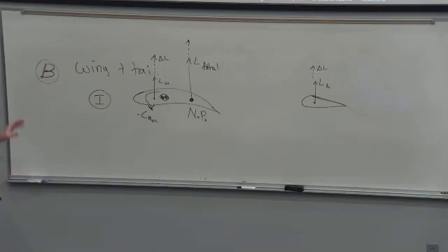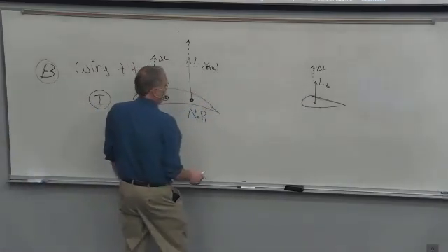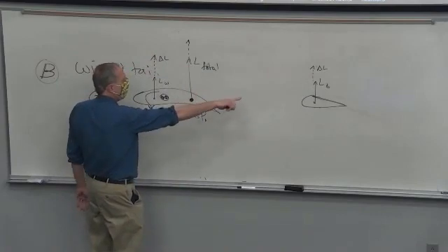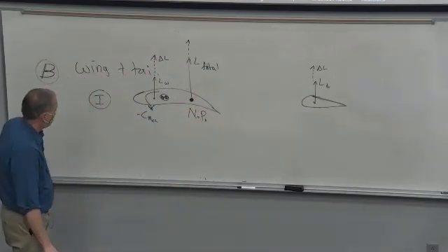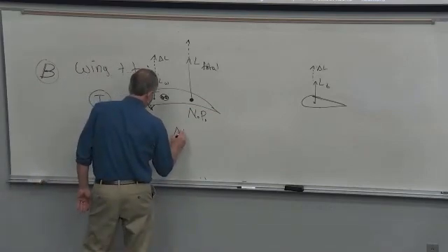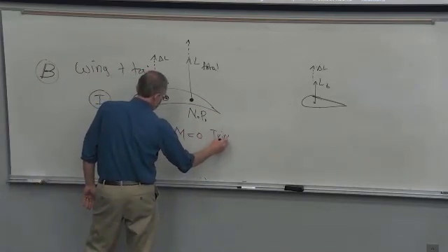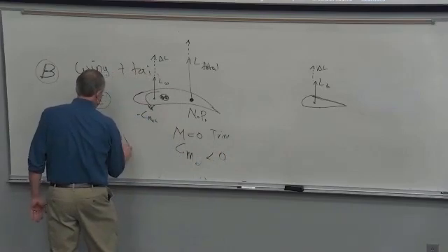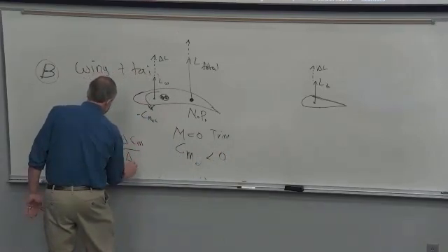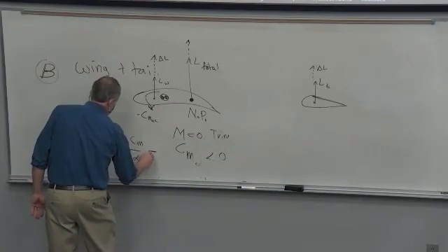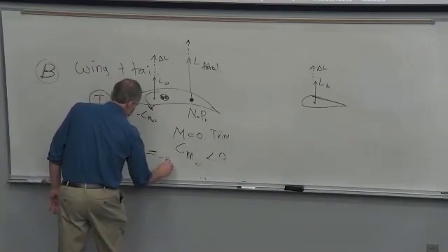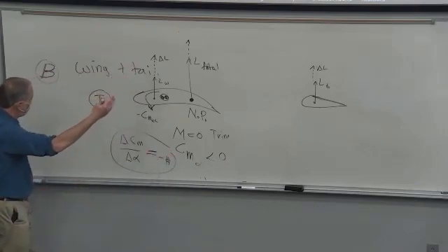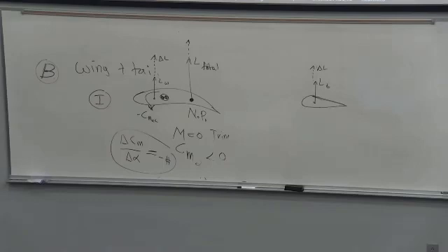And it's the wing relative to the size of the tail and how far back the tail is, right? Because in a distributed load, you're finding the resultant of these two lifts. This point is going to be determined by how big that is and how far back it is. So with this case, you can get trim, and you can get pitch stability. In other words, a change in pitching moment with change in angle of attack is negative. So when alpha increases, you get a nose down or negative pitching moment that counteracts it.